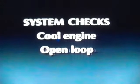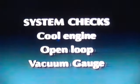While the engine is still in open loop, make sure that the EGR system and canister purge are not engaged and that the EFE is. You should also check to see that the air management system is sending air to the exhaust manifold to warm the oxygen sensor and catalytic converter. These system checks are pretty easy to complete, but remember, the engine must be cool and in open loop. In addition, all you'll need to make these tests is a simple vacuum gauge.